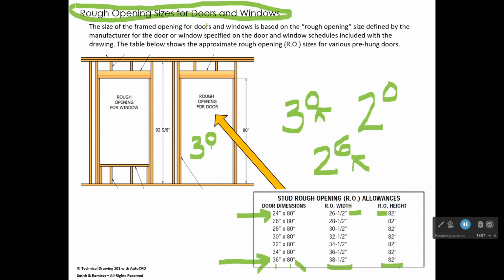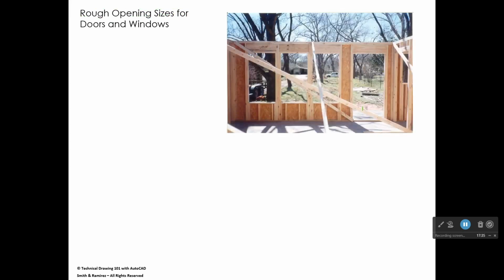And usually what we do, we'll just type 3-0, for example. We would type 3 and 0, and then we would double click on that text and highlight the 0, and in our text setting we would set this up for superscript, which is one of your options up there on your text editor tab. So you would just change that 0 to superscript, and that moves it up and makes it a little bit smaller usually. So we'll use superscript for those.